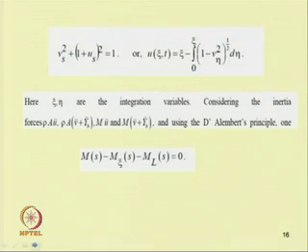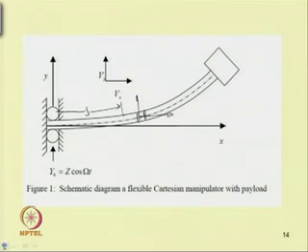Taking those inertia forces, we can find the moment at a distance zeta. So, one can find this bending moment. First we can find it for a single element, then we can find it for the entire beam by integrating. Also one can find the moment due to this end load. Let m be the mass of this end load.